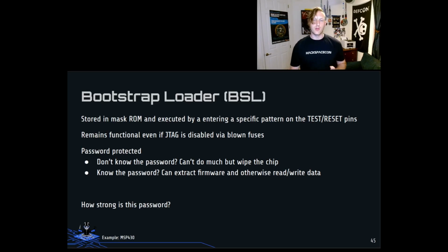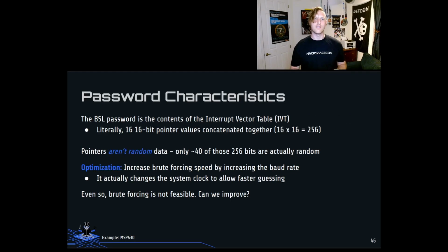So this bootstrap loader is always around, and it's password protected. If you don't know the password, there's not too much that you can do other than wipe the chip. But if you do know the password, then you can read and write memory, and you can extract firmware and otherwise get full access to the chip. So as we look at this, what is this password and how strong is it?